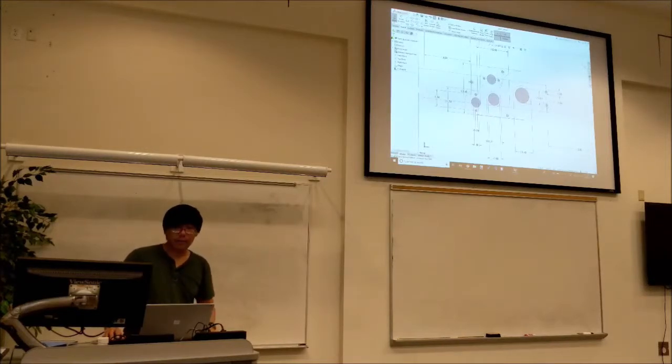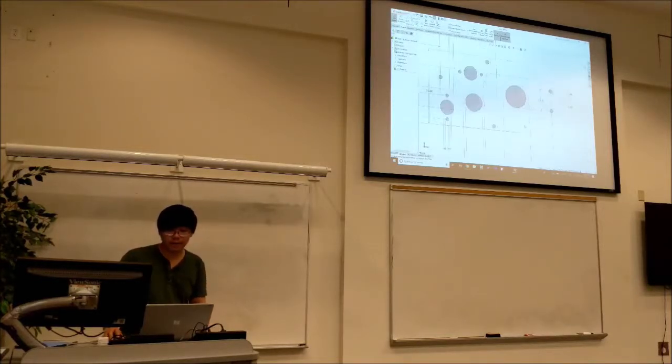So now most of this is basically every single hole that's going to be in our plate, right? So this is basically our gearbox design. All we need to do now is close off the plate to make it one closed contour, and then we can extrude it, and it'll be our 1/4 inch plate. This is just connecting the dots, essentially, connecting where all the outlines of your components are. So you can just use tangency to make straight lines across and form the shape of your gearbox.